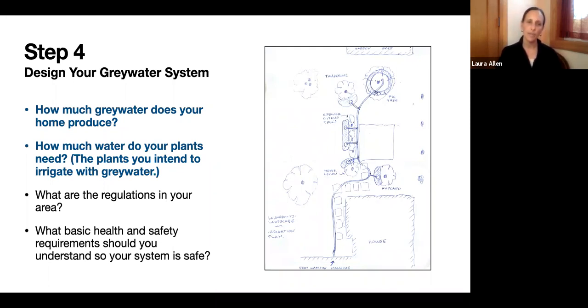On the other hand, if you have a pumped gray water system and you've gone to one of the more complex systems where you have a filter that's automatically cleaned, some of these filters are backflushed with clean potable water. And so with that type of system, you have a potential to have dirty gray water connecting into the same lines as clean drinking water. You never want dirty water to get into the drinking water line. So those systems require backflow prevention to make sure that can't happen. So they require more oversight. There's definitely more that could go wrong.